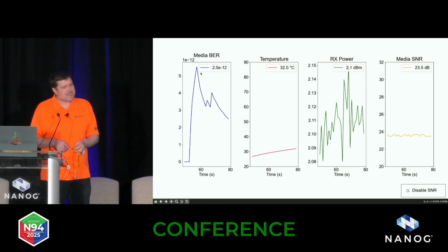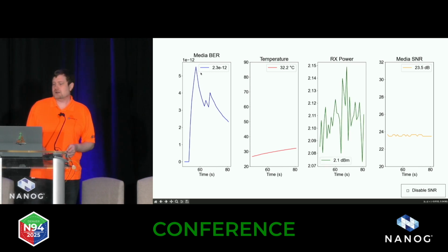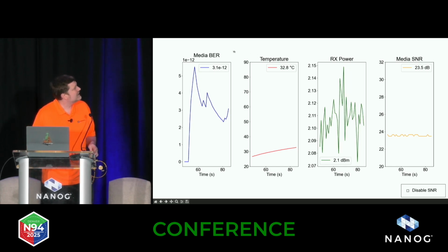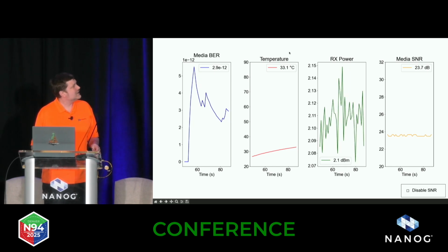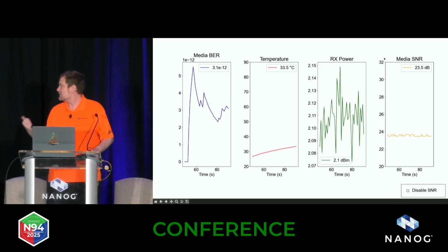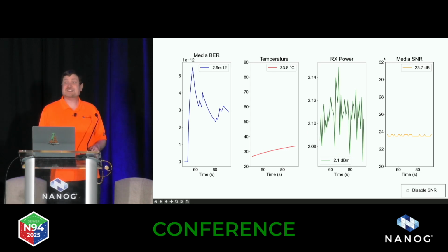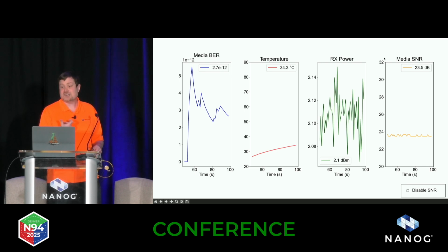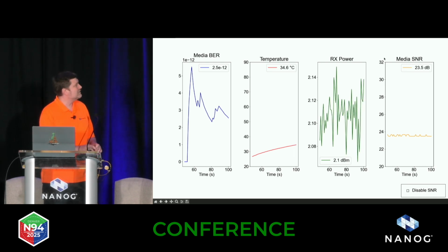And there's one challenge with measuring all this. You have registers where you read out the memory, but the thing is, media bit error rate and media optical signal to noise ratio, these two views we were talking about in the first slide, share the same memory. So what you have to do is write a value into the register, a diagnostic selector, in order to swap. And that is what is happening here.